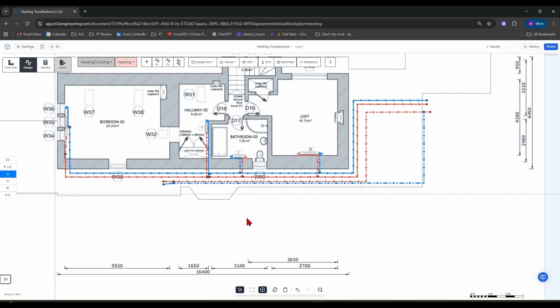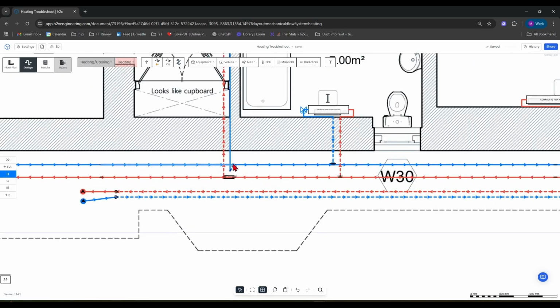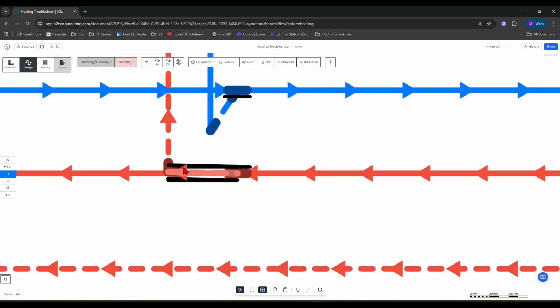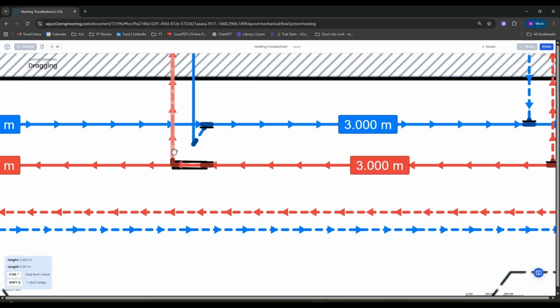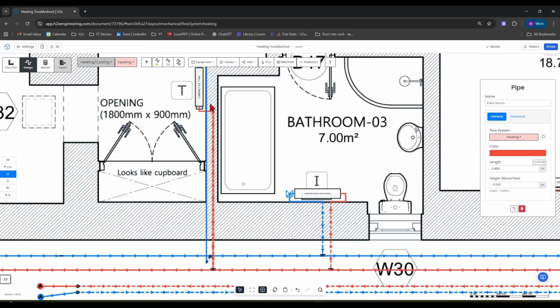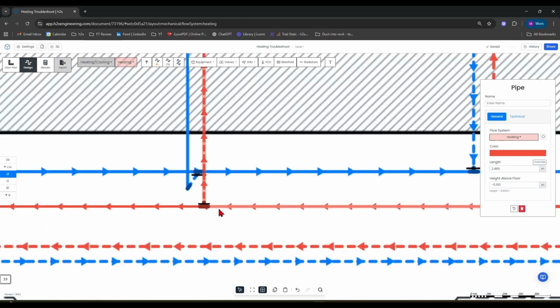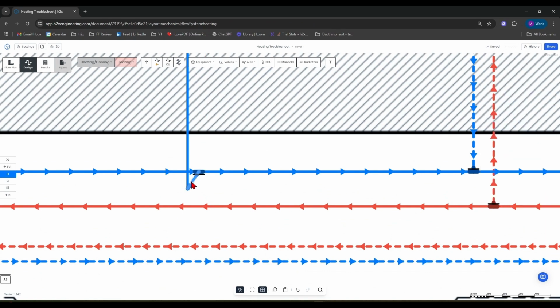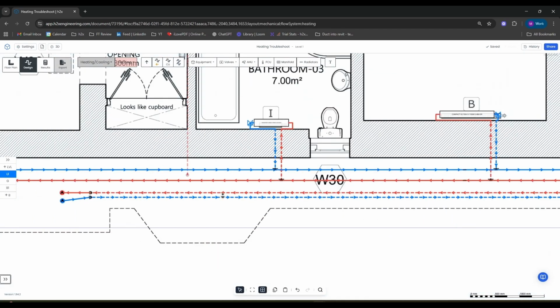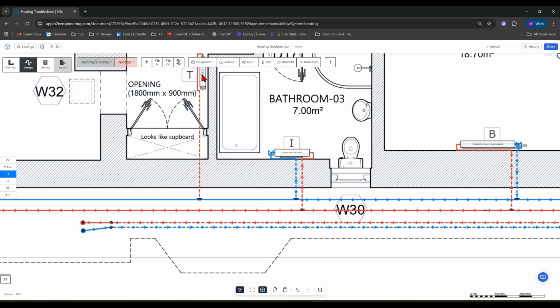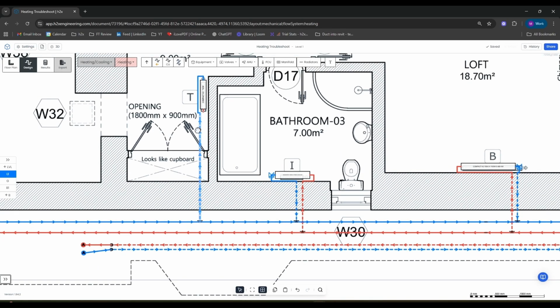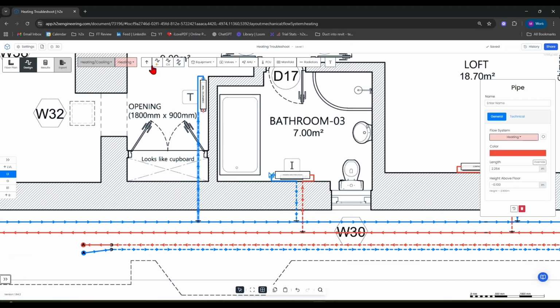Now, if we take a look at some of these connection points, these black lines mean that you have overlapping pipes. So what I would do in this situation is drag that back over to there, but take a look how that affects this part here. And maybe just go ahead and delete these connections and neaten it up this way. Left click and drag that over there. Got a kink in our pipe there, so we can drag that straight.